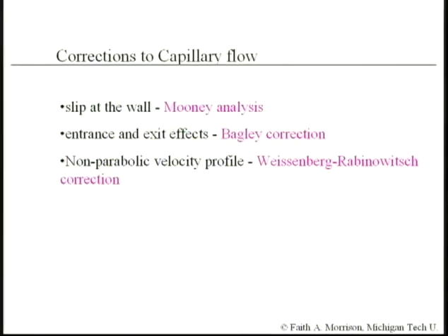So that is one of the main corrections that we use in capillary flow, but there are actually two others, and I want to talk about them next. One is the analysis due to Mooney that takes into account any possible slip at the wall. And the second is the Bagley correction, which takes into account those entrance and exit effects. I added a few slides this afternoon so I can show you how those calculations look.